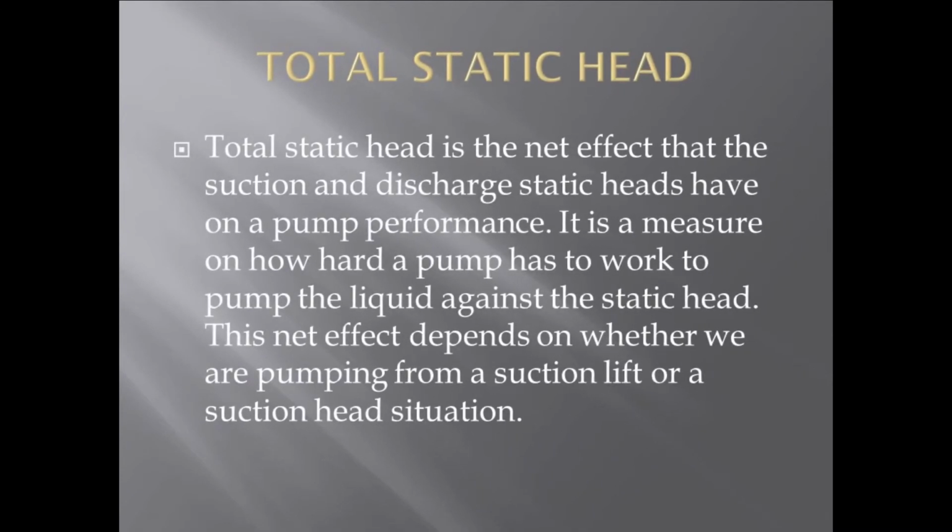Total static head. Total static head is the net effect that the suction and discharge static heads have on pump performance. It is a measure of how hard a pump has to work to pump the liquid against the static head. This net effect depends on whether we are pumping from a static lift or a suction head situation.